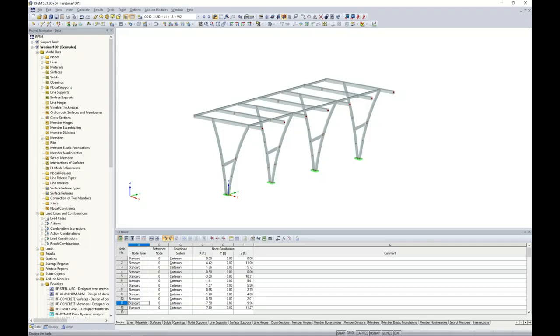But today, what I do want to apply is the reduced stiffness requirements from section C2. And the code tells us that we do need to reduce the flexural stiffness by a tau sub b factor. And the tau sub b factor is an equation and it needs to be iterated based on the axial forces within our member.